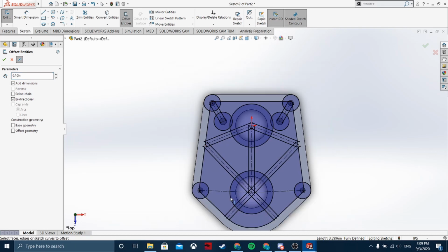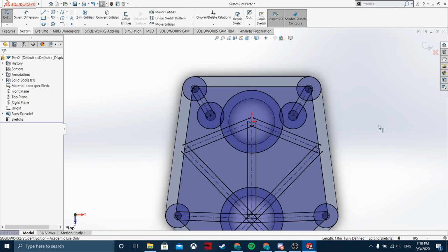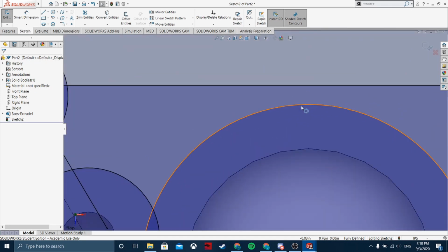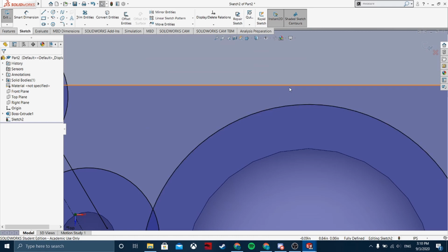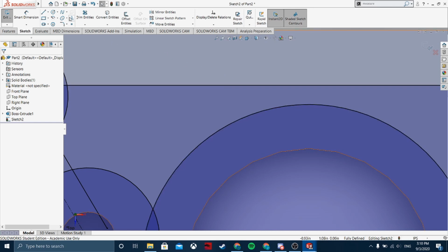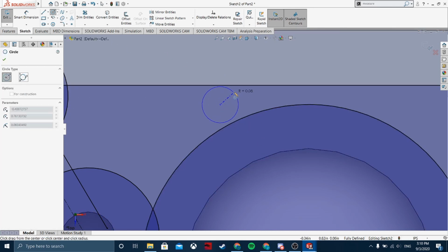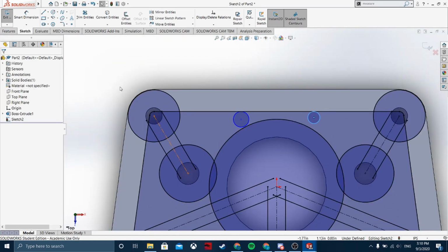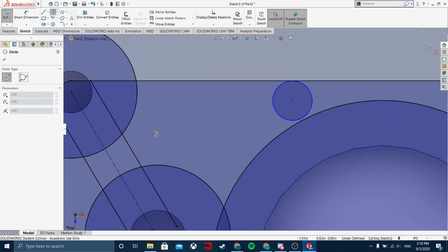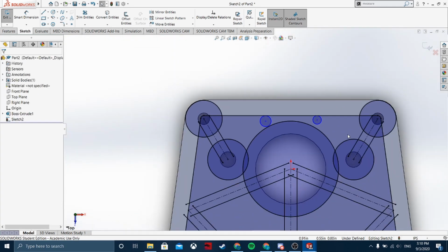This time, when we're filling, remember how we had to make those circles? We gotta do the same thing here. Like for example here, how are you supposed to fill it when the line and the circle don't even intersect, right? So that's where the circle comes in. Do that, make a tangent, do that, make a tangent, and do the same thing like last time. Okay, this I think could fit. I could check that here. Yeah, the radius is already 0.16 and it fits pretty well.